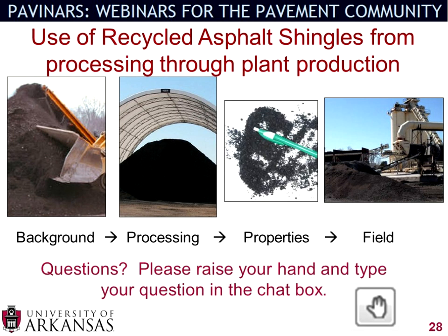I think the biggest thing that comes to my mind when you're thinking about using any warm mix technology is the fact that you're not getting as high mixing temperatures in the drum for the blending of the RAS asphalt cement and the virgin asphalt cement. Now, it's my impression that we haven't had a whole lot of problems using RAP with warm mix foaming techniques.